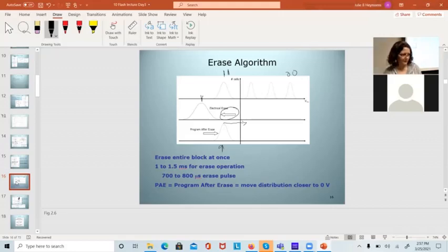Does that make sense? If we can program a 0, it's just not something that's ever actually used. Is that you erase the entire thing and then reprogram it all back? Yes. You erase the whole thing, and you erase them below that level. So then you've got some program and verify headroom here. Instead of just saying whatever random value they erase to, I have to add a little extra charge to get them to their lowest threshold state.